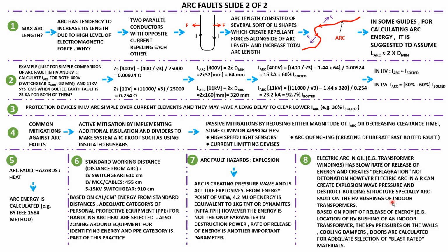It's very important. I've dealt with many of these cases where an explosion damaged or collapsed the building, and most of them had been overlooked by engineers. They just put a 2 hour fire rated wall around the transformer. A 2 hour fire rated wall is okay, it protects from the fire, but explosion is different. And in some specific cases, especially indoor transformers, it could create a massive pressure wave, like the explosion of a bomb inside the room, and damage or collapse the whole building.